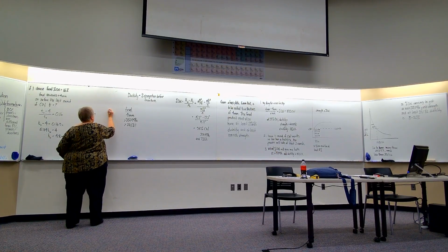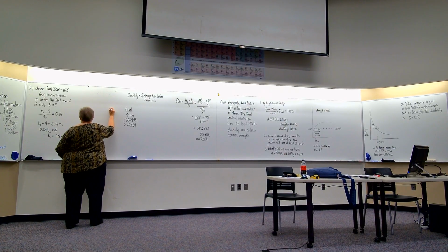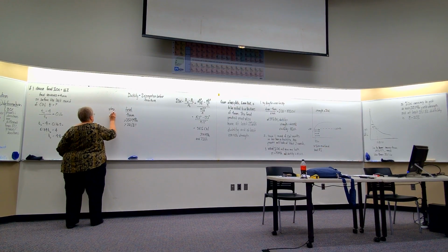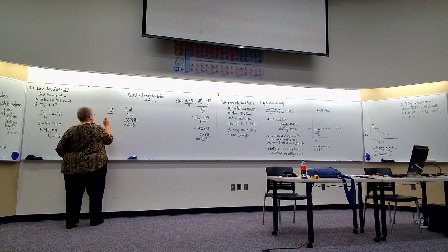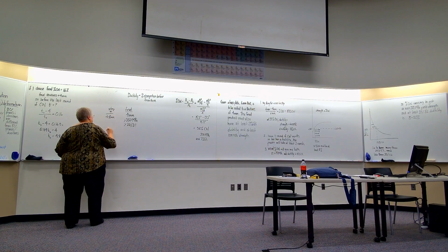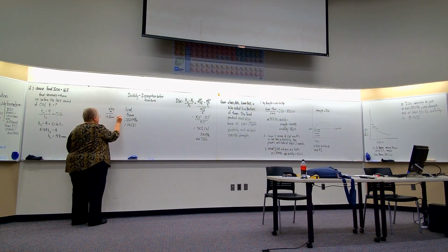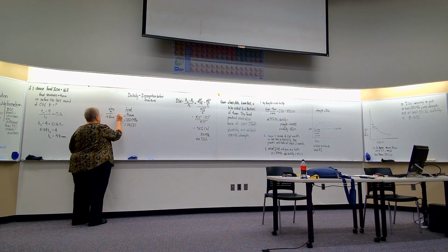The step before that, I don't know how many steps there will be. Let's pick 4. And we might not end up with 4 steps. But in step 4, I need to have 4.8 millimeter diameter so that I get a 16% cold work.